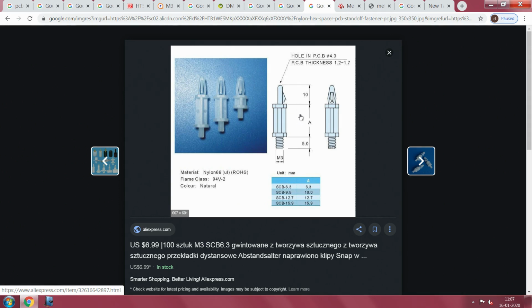Why I thought I will show you is, there are things which lock on both directions, there are things which lock on one face. So, in your assembly drawing, you can also give an indication saying this locking tab should only face one particular direction. In case you have a component stuck here, if you have the locking tab there, it is going to damage it.